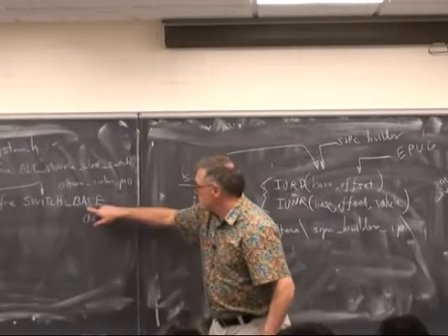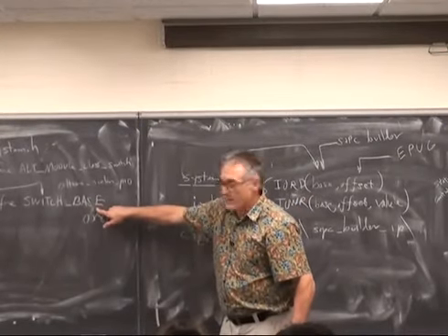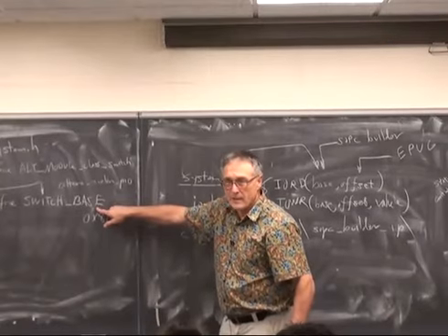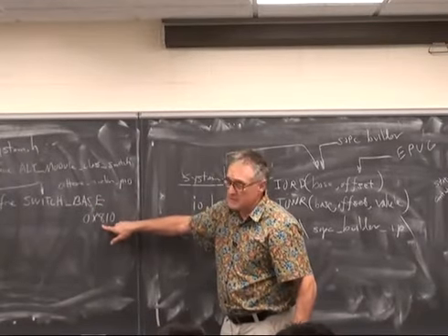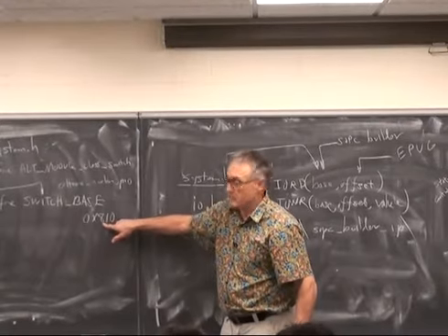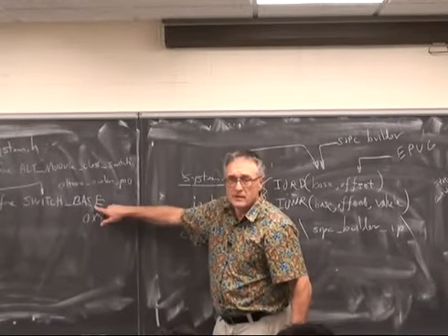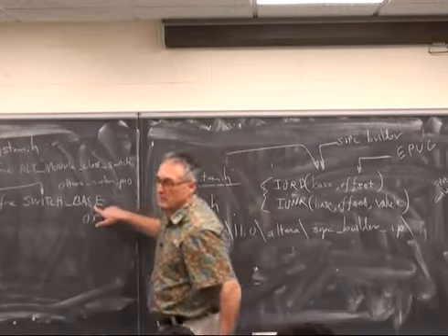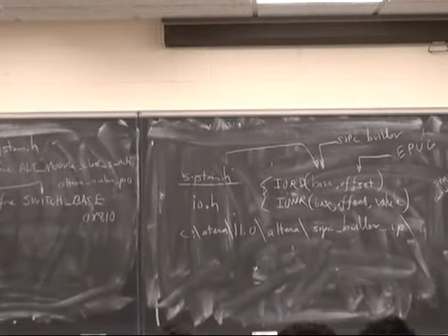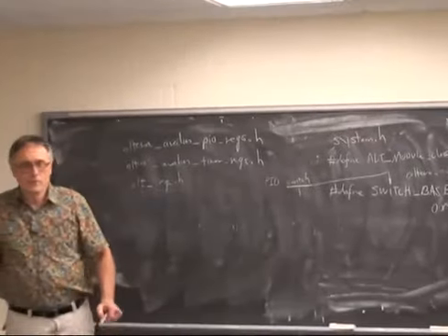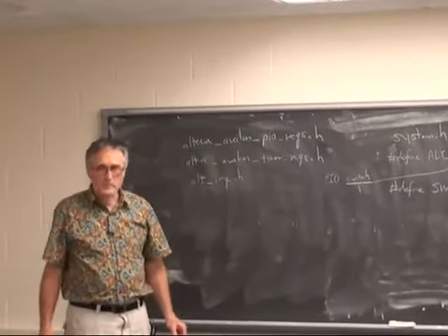Use switch base. That is the symbolic name that corresponds to the absolute address. You can use the absolute address at your own risk, but why not use the symbolic equivalent and save yourself tears trying to debug when what's wrong is you're no longer actually writing to the I/O port.